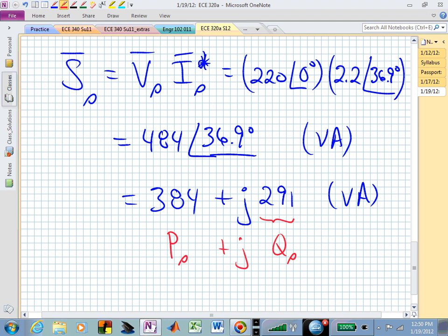And I can say it's magnetizing. It's supplying. It's not absorbing or delivering. Actually, this is delivering 291 magnetizing VARs. It's giving the system that because it's an all-inductive load, isn't it? It has to deliver those magnetizing VARs. Questions on that?